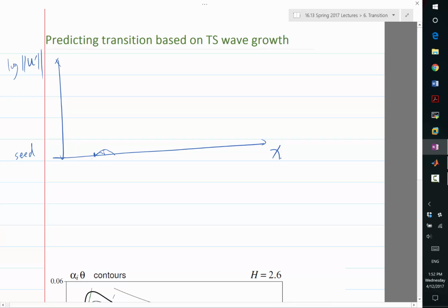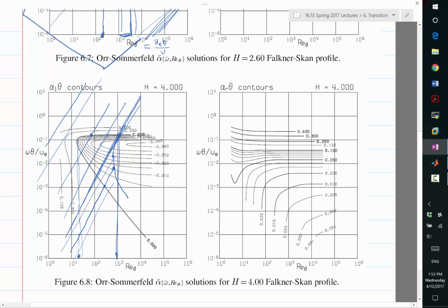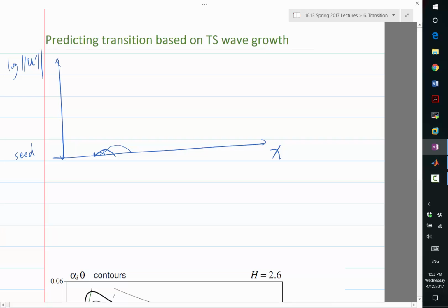But this is one particular frequency. So this is the highest frequency. And later on, another curve starts over here, but enjoys a larger range of growth. That corresponds to different lines through this instability region. Later I can have a curve that goes like this for a different frequency, and yet a different frequency like that. So for each frequency, starting from here to here is the region of growth.